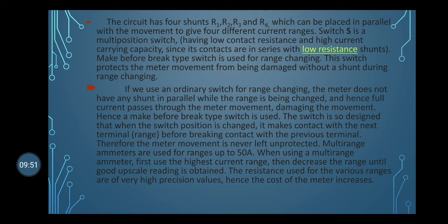In the case of a make before break type switch, it makes the next resistance before breaking the last resistance, and by using this, it protects the ammeter from damage.